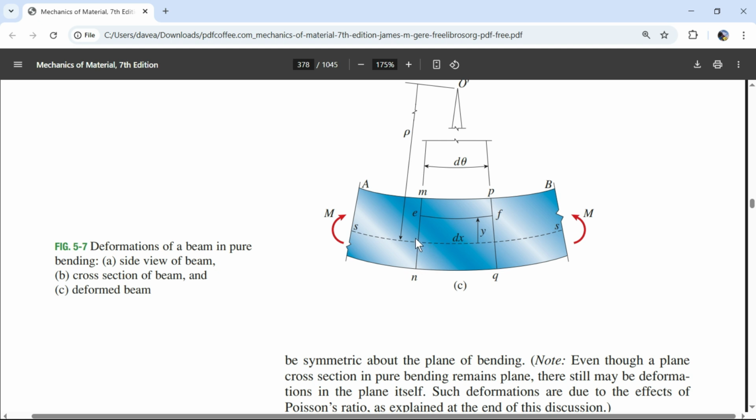It doesn't really have it on here, but that's what it is. So if this original length, I always like to use 1 meter because I can break 1 meter into 1,000 millimeters. And with steel, it can only lengthen or shorten by 0.2%. That's going to be multiplying 1,000 by 0.002, which gives 2 millimeters.